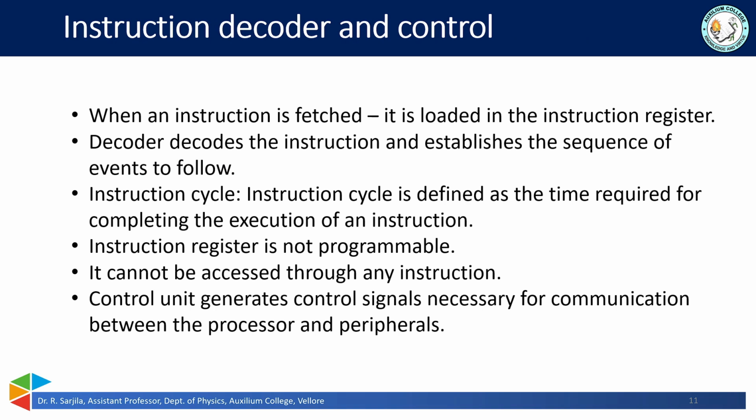Timing and control unit. This unit derives all the necessary timing and control signals required for the internal operation of the circuit. It also derives control signals required for controlling the external system bus. Oscillator. This circuit generates the basic timing clock signal for the operation of the circuit using crystal oscillator. Instruction register.